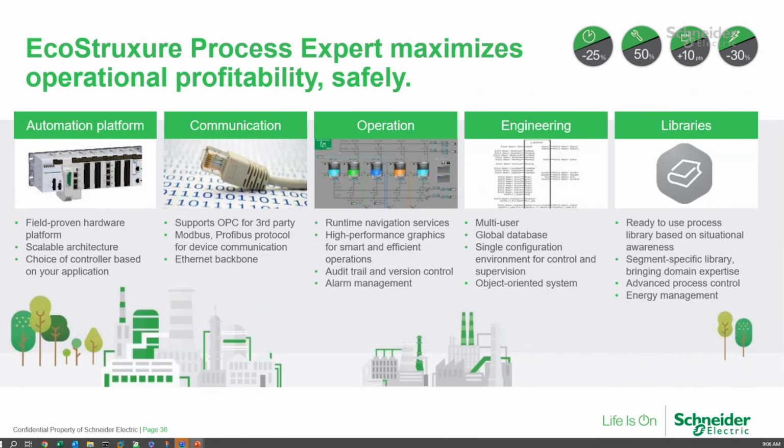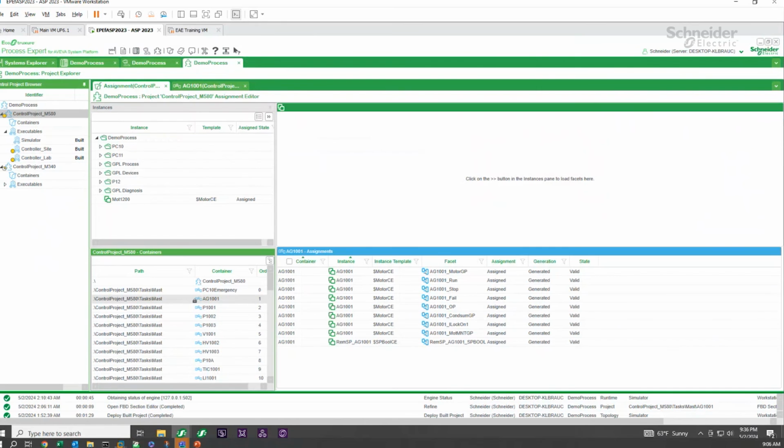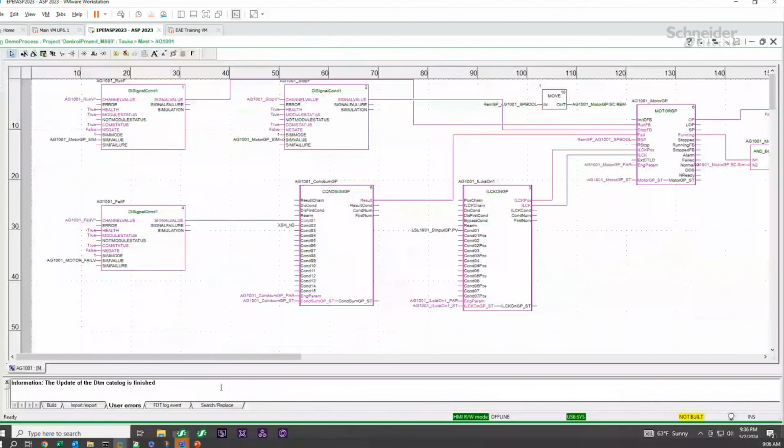If you look at Plant PAC, for example, they really want this run in specific controllers that have the library built into the operating system, into the firmware, because they're hugely resource intensive when they run Plant PAC. Here we're using standard DFBs, and you configure each object instance. Let me get back to our screen here, and we'll look at that logic again.